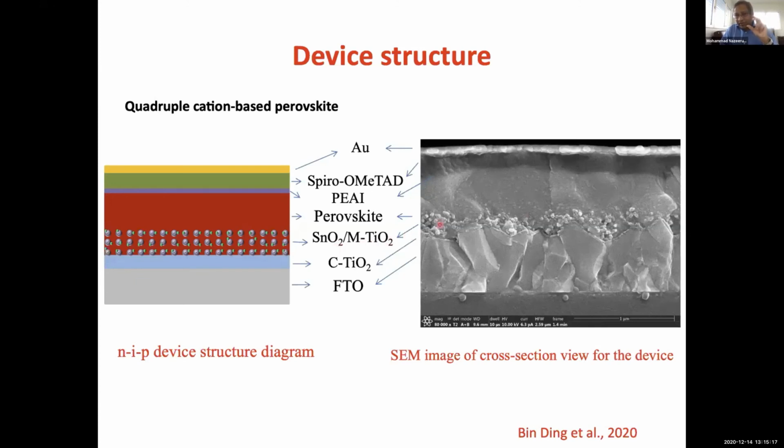This is a very small layer, around 100 nanometers, as shown here. This particular layer is an interface between the perovskite and the electron transport material. The bilayer configuration we discovered is very important in order to stabilize this material, as you will see towards the end of my presentation. Now, this is the perovskite composition. Here you have an opportunity to tune the composition so that you make this material extremely stable and high performing.